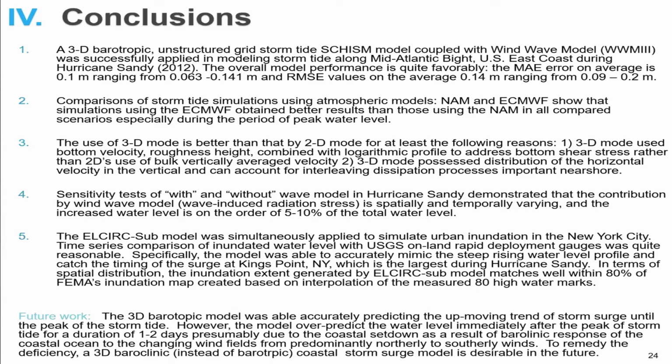And we think 3D mode does better because of two reasons. One is it resolves the boundary layer induced shear stress rather than using 2D's vertically averaged velocity. And number two is that the 3D model can have a distribution of velocity in the vertical and can account for this interleaving dissipation process, important near shore.